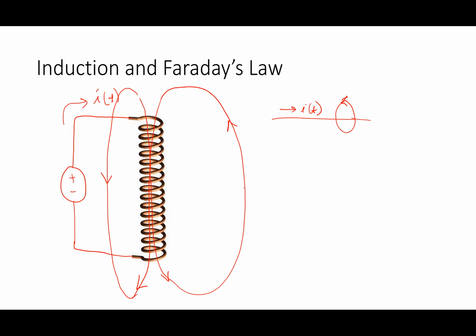So over here, right, if I take a coil and I stick a coil right here, what's going to happen to that coil? There's going to be a voltage, right? And I like to say it that way. There's going to be a voltage because if it's open, I get an open circuit voltage there. I don't get a current because there's no closed path for current to flow. But I'll get a voltage, and if I stick a load on that, then there will be a current.